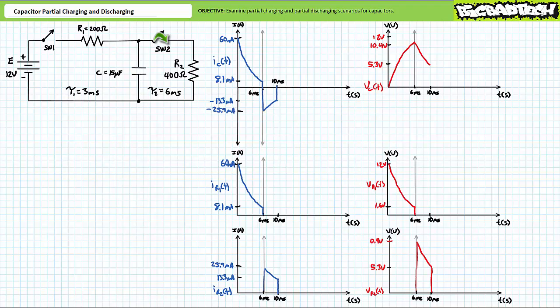The larger circuit's t equals 6 milliseconds is kind of like the partial discharge phase's t equals 0 milliseconds. If you want to, you can add accessory vertical axes to remind you of the switchover. All you really have to do is reference any previous time values from this new start point. For this partial discharge scenario, switch 2 reopens 4 milliseconds later at the larger circuit's t equals 10 milliseconds.